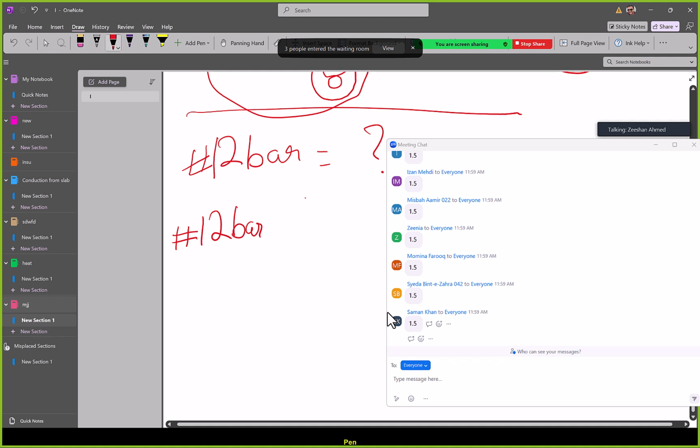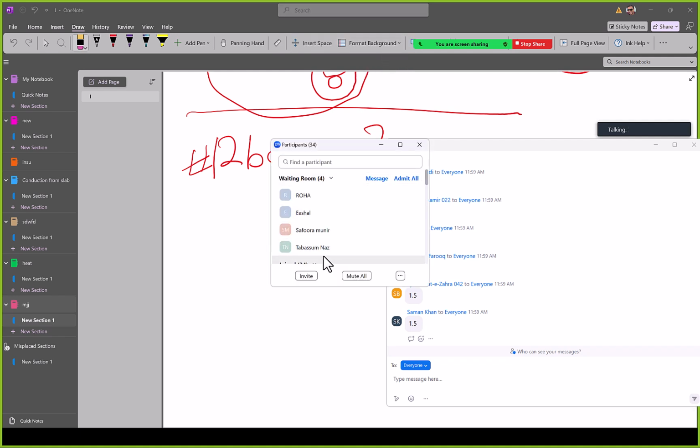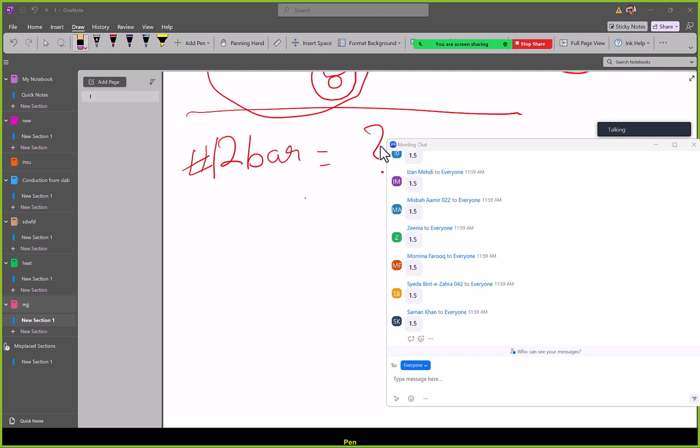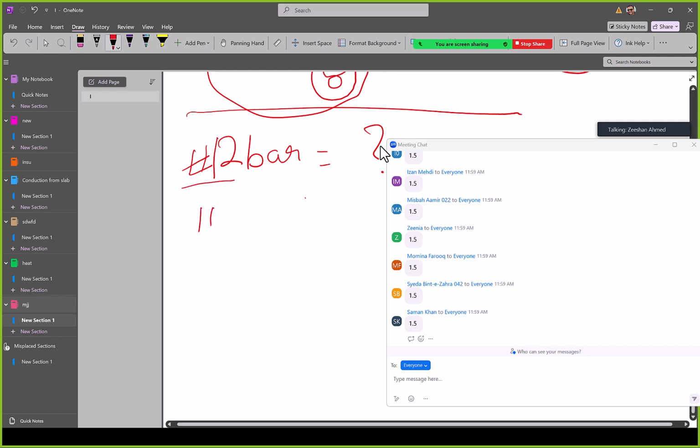So again, one final time: the designation of a number bar, that number divided by 8, in inches, will be the diameter. Okay? Not area, not radius, but diameter.